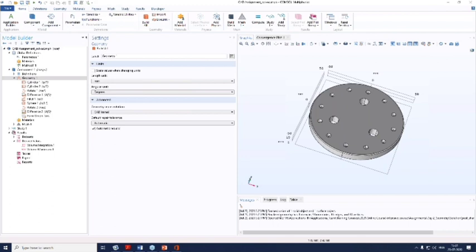Yeah, a 6-layer piezoelectric micromirror geometry can be built by starting in the 2D builder. We cannot say whether it can be started in 2D or not. Again, it depends upon how the design looks. For example, if it is just some 2D cross sections which are getting extruded or revolved, then yes, you can start in 2D and then extrude or revolve some parts.